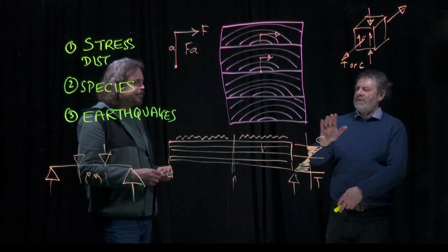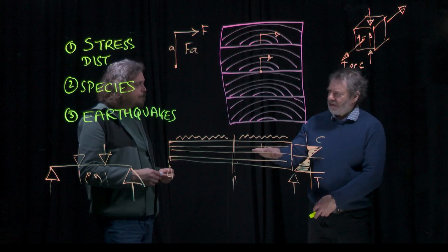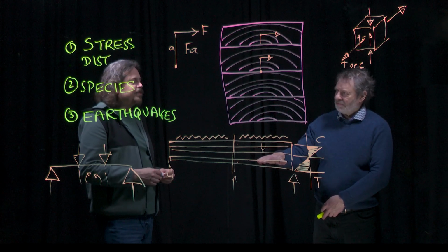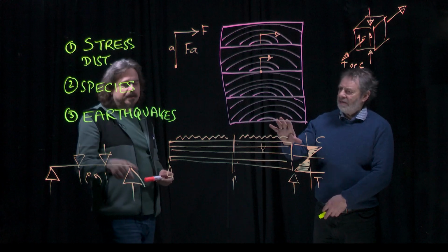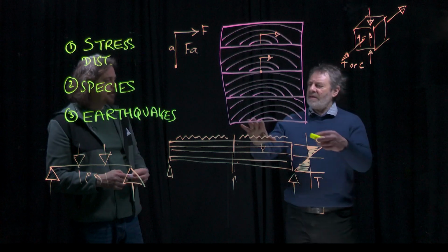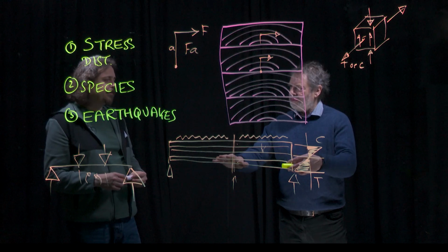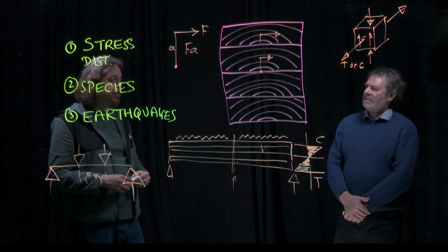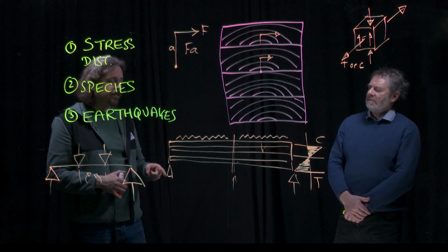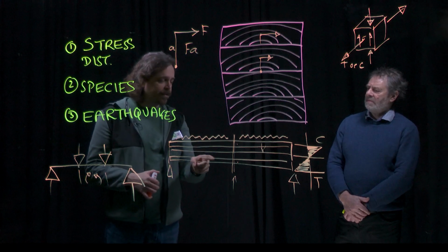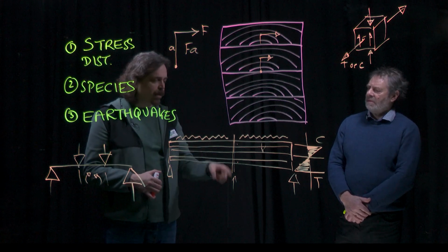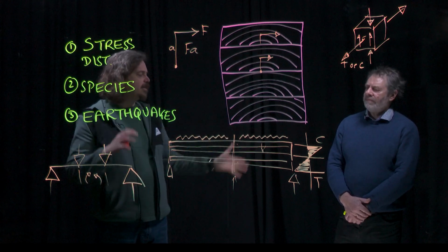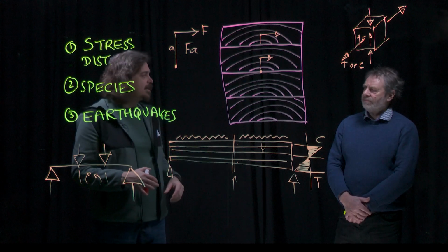So the timber before it goes into glulam is going to be graded? Yes. Always, strictly according to the standard? Yes, it's the European standard. Because of that, the glulam will be predictable, or do you have to then test the glulam afterwards? You can do either, actually. Normally you would look at the grade of the lamellas that you put in and use the process in the standard to work out what grade of glulam that results in. No need to do any testing, but the standard does allow you to do testing if you want.